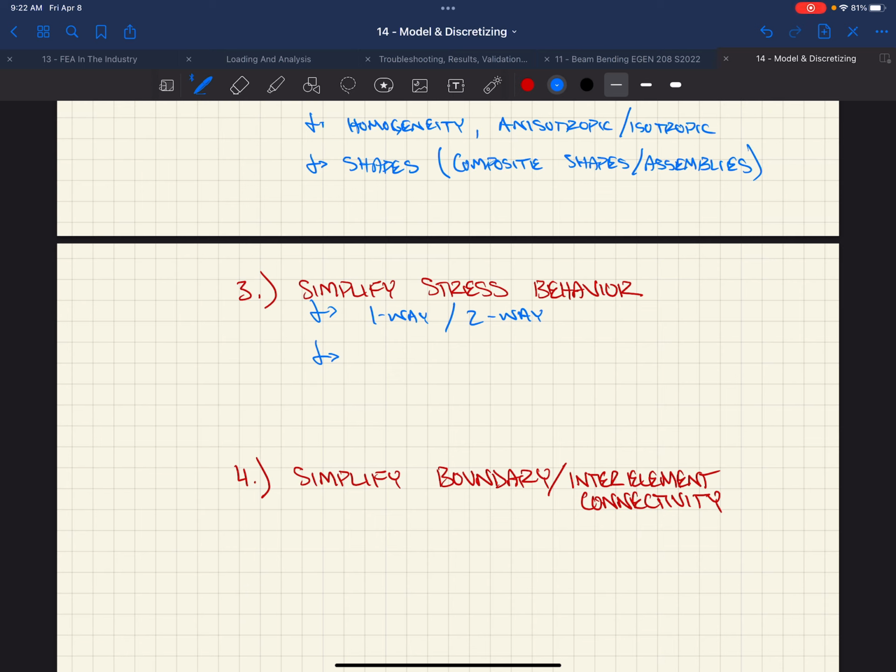And the load is going to be spanning like this. That's going to do a lot different than if you said that this thing spanned one direction. Because now this member has this much tributary area versus that much tributary area. And you got to think about how you're doing that also.